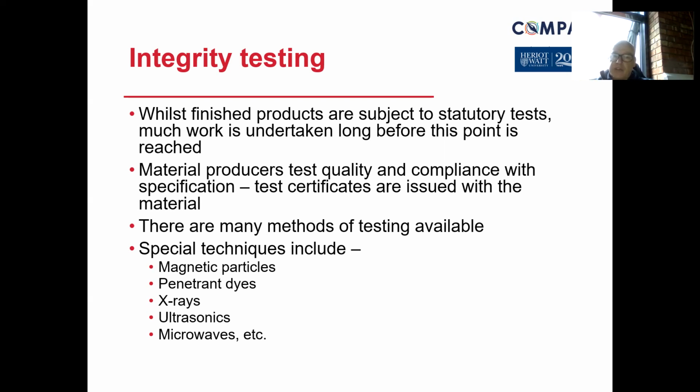But then the non-destructive testing allows us to perhaps get inside the material, X-rays, for example, or magnetic particulates. So what you can do is you can put a dye on it, and if there are any cracks in the metal, when you put ultraviolet light over the top, you can see the glow where the length of the crack is. And that eventually, with it being non-destructive, you'll say, well, I can accept parameters.